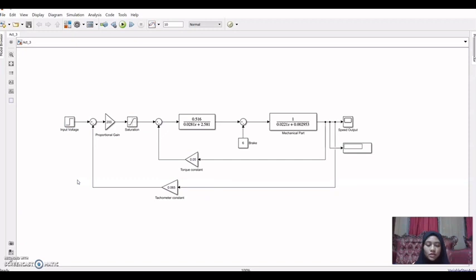So after setting all the parameters, I can run the simulation to obtain the motor speed value according to the brake value, which is 0, 3, 6, 9, 12, 15, 18 and also 21. After that I also have to show the graph obtained.